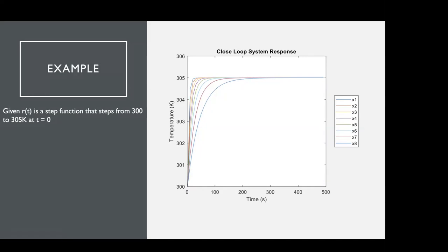I'm not sure how you would fix it within a range, because in steady state error you're basically using the final value theorem, where you assume you're tracking your reference input, and when you track it, you get the equation for G. But if you had noise in your system and said, because I have this noise I can't actually control it to this value, but I want to control it between these values, that's not an issue, because Kalman filtering is statistical modeling, like a Gaussian, where you estimate your state statistically and have a really accurate model of where you were.